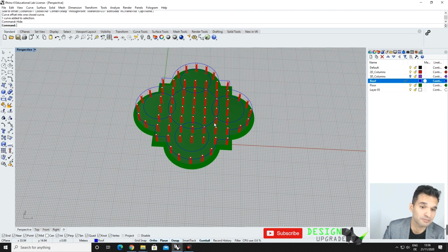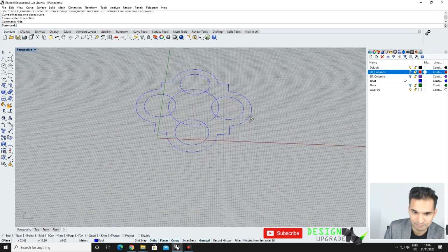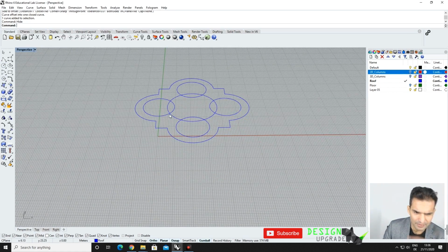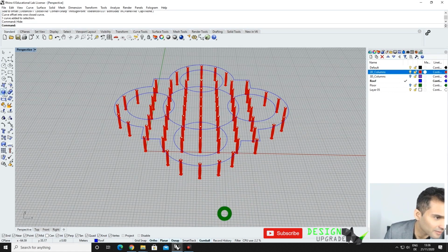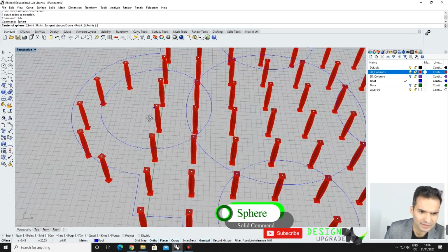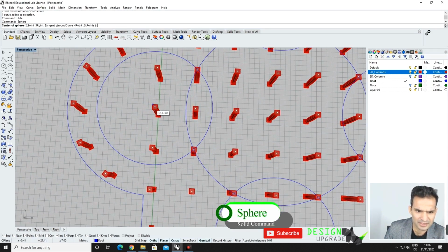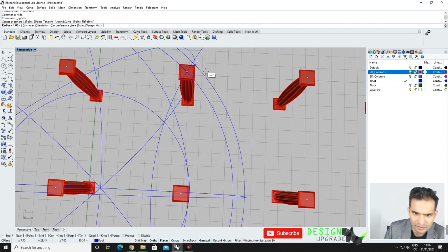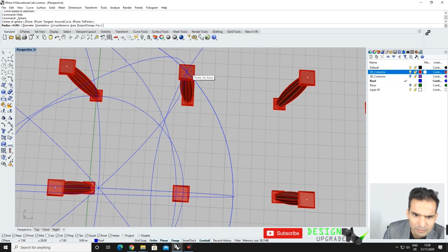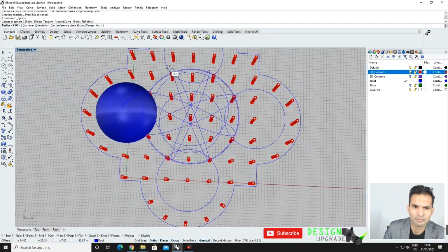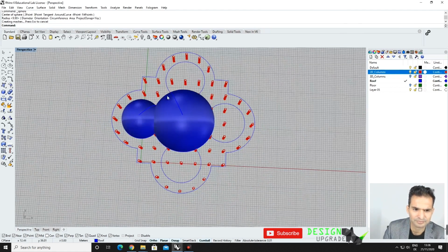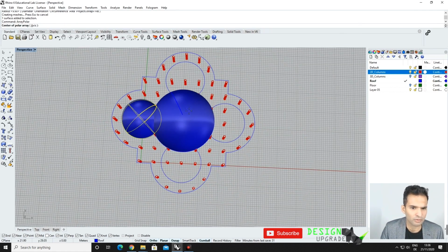And now what we want to do is just basically create spheres. So let me just get rid of floors and also our columns. And now let's just create spheres. And we need to find a center point. So maybe the columns I can leave. Get the sphere command. And now the middle of this is here. So I go all the way until I find this point. Yeah. Then I can take this and find the point here. And this I can just array polar here, for items.